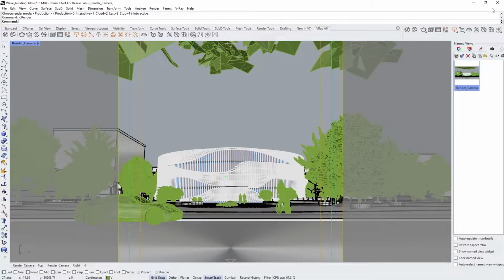Now that the scene is done, we can prepare the project to be shared with colleagues or rendered on a farm. Notice that when we download assets from Cosmos, they are stored in our local machine. In order to avoid missing assets on other machines or network rendering, we will need to do a few additional steps. If we want to render our project on a network render farm, we need to pack all of the Cosmos assets with the project. But if we want to share it with colleagues, there's another option to be sure that everything renders as it does on our local machine.